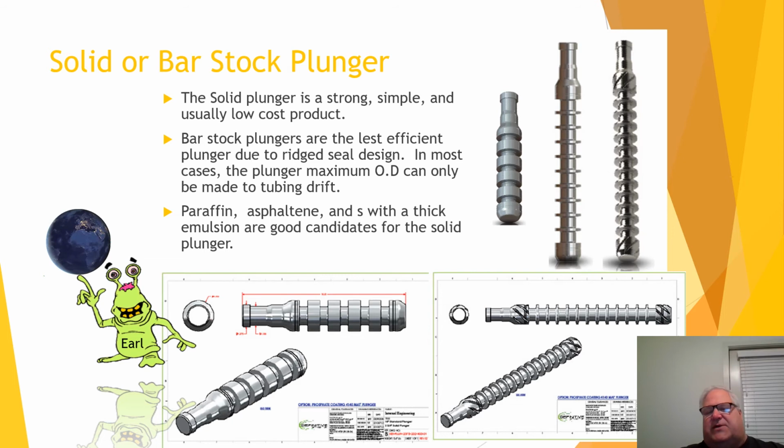These ribs, or these vents, or whatever you want to call them, the veins do spin that plunger. As that plunger is falling, it'll typically stop it from always landing on that one side, or even if it's falling, it'll spin enough that it doesn't create that saddle. I would call it saddle. I don't know if that's the right word, but then you're able to wear those plungers more efficiently.